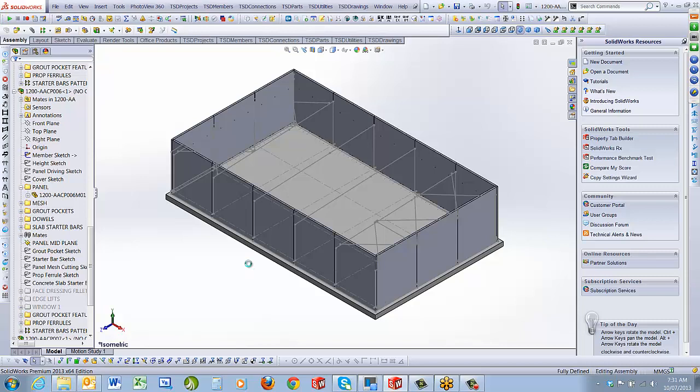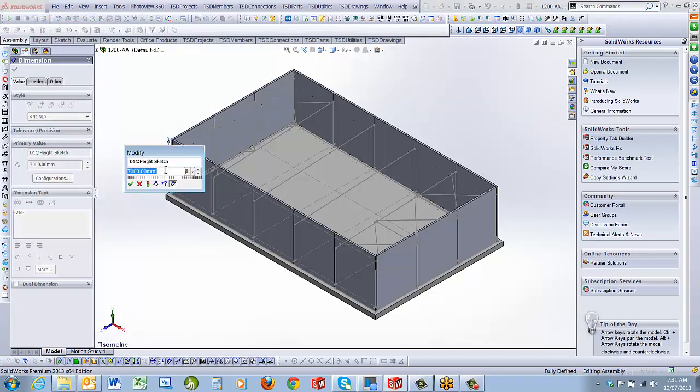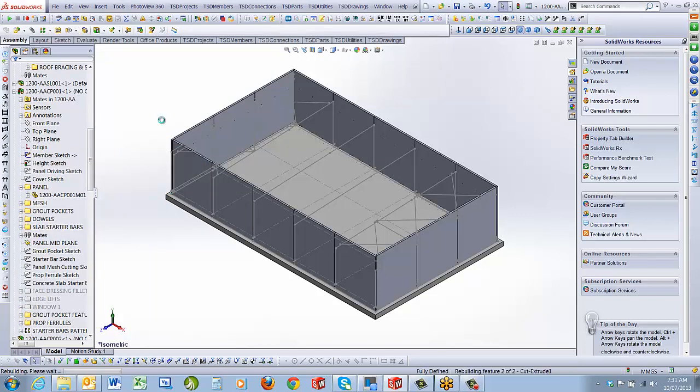Now, what I'm going to show you is that we can change the heights of the concrete panels in one go. I've got a new feature in TSD that allows us to use match dimensions. So this panel here, if I make it the original panel for the matching of the dimensions, what I want to first do is just go in and grab the height sketch, and if I wanted to make it, say, let's just go 8 meters, and we have quite a high sort of parapet arrangement happening on that panel. So now I'm just doing a second rebuild. Okay. So now I'm just saving, just Control Q and then Control S. So now we've got ourselves a driving panel.